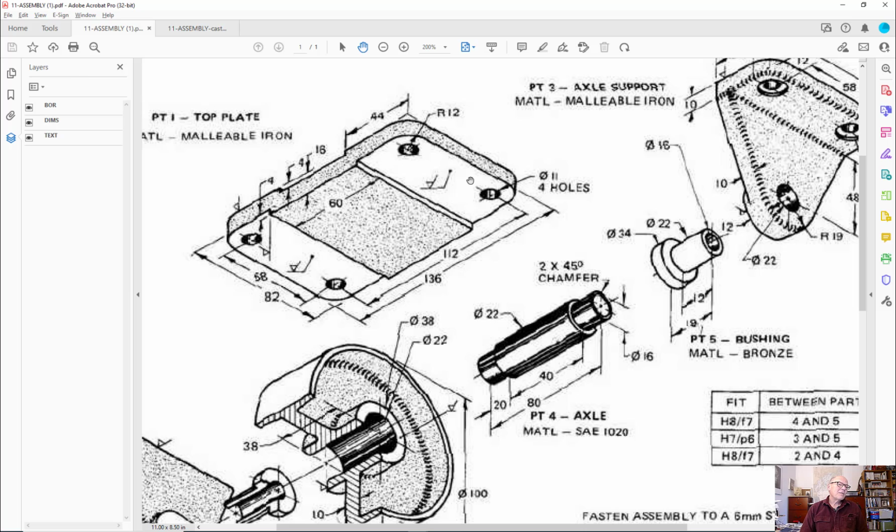And then we don't need to worry about the depth on this until we do the side view. So all I want to do is draw this from one point of view where we see that little cutout, and then we see that little protrusion that comes down. And I'm going to go ahead and draw the hidden lines in there as well, representing the holes.